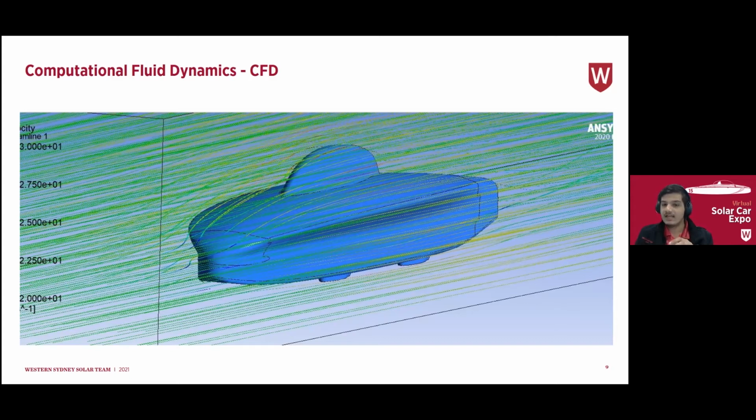This includes how the air is entering the wind tunnel and at what speed, and how it's exiting the wind tunnel area. You can set your ground to be moving to better simulate the real world. And you can also set your tire surfaces to rotate in order to capture the complex interaction between an exposed tire and the air.